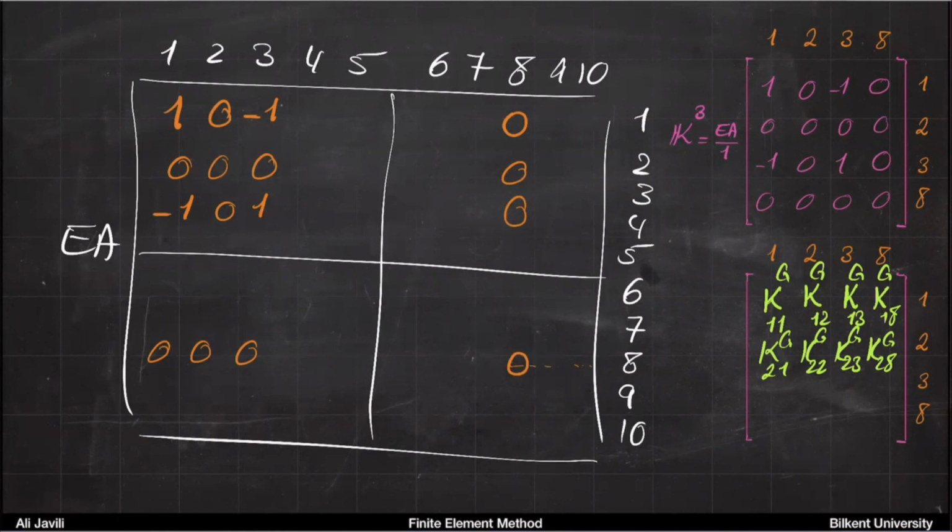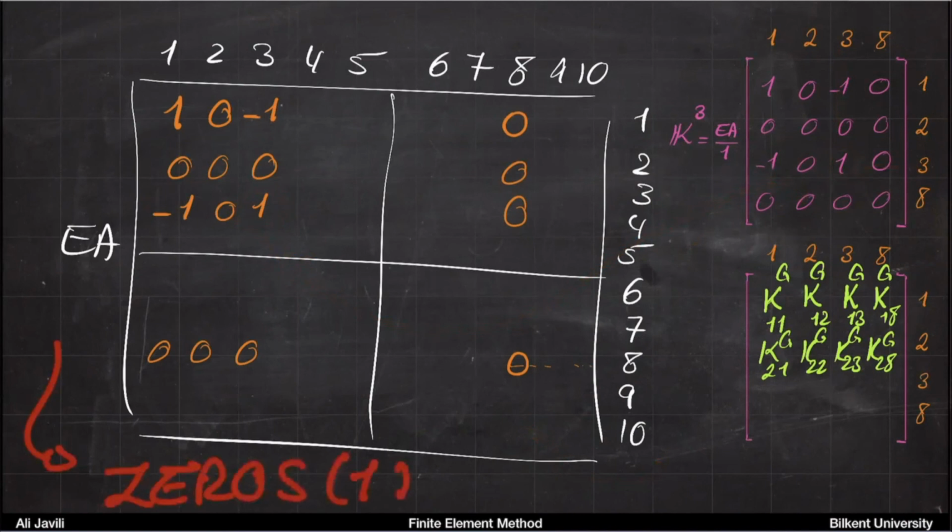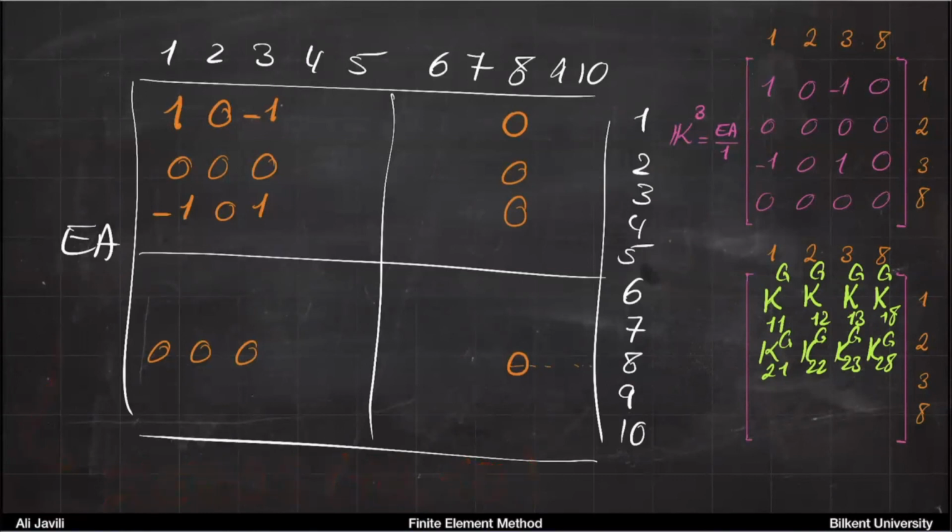So again, if you have done everything correctly, this is just some loop in your computer, and then you have a matrix here, it's 10 by 10. You would just say, okay, read this component, look at these associated numbers, and then add it where it should go to the global matrix. So you just create a matrix which is, we usually say zeros of 10 and 10. So 10 rows and 10 columns, it's all zeros. And then you have a loop over your elements, and then you keep adding these numbers to that matrix.